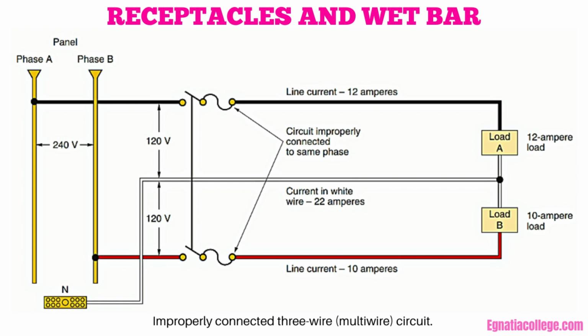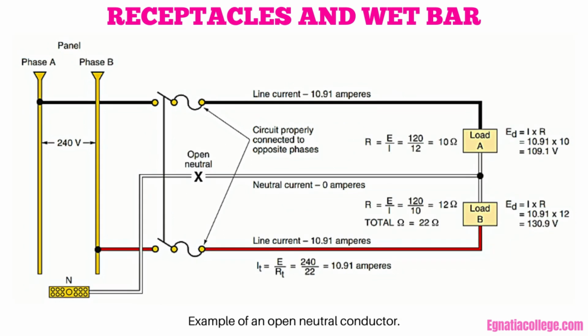If an open neutral occurs on a 3-wire circuit, some electrical appliances in operation may experience voltages higher than normal for the circuit. This figure shows that for an open neutral condition, the voltage across load A decreases and the voltage across load B increases. If the load on each circuit changes, the voltage on each circuit also changes.